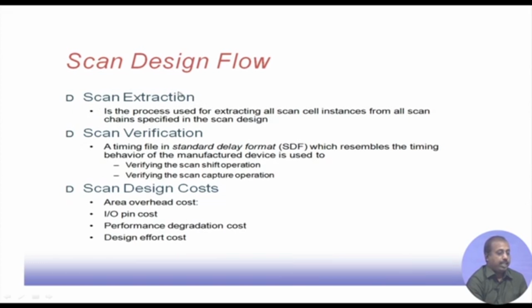Then we have scan extraction. It is the process used for extracting all scan cell instances from all scan chains specified in the scan design. This will find all the flip flops and latches that have been converted into scan cells, and in which chain they exist.